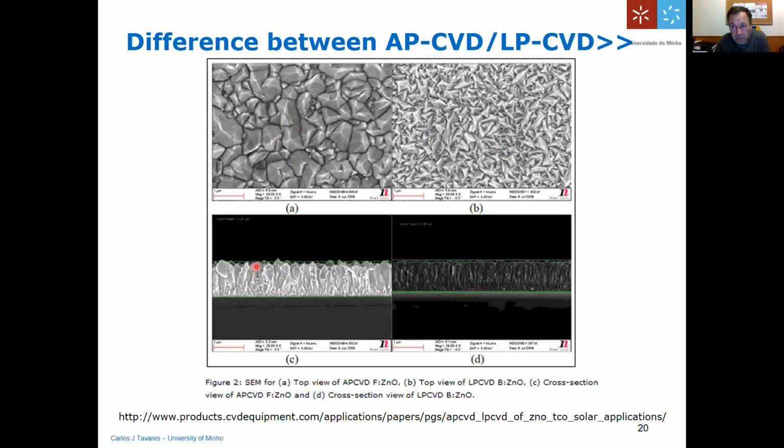But on the other hand, zinc oxide is a transparent layer, and if you dope it with fluorine, normally it can become electrically conductive, and you can use this as a top electrode on some solar cells, which are transparent, so the light still continues to go down towards the active part of your photovoltaic material, and this is only an electrode, where you can harvest the electrons which are generated from this process, okay?